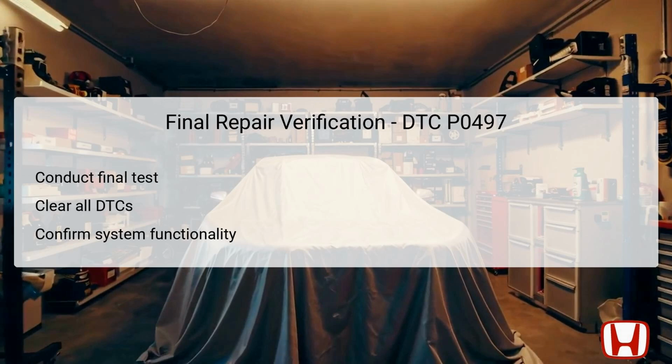Start by clearing all diagnostic trouble codes using the Honda Diagnostic System, HDS, to reset the system. After clearing the codes, it is vital to run the EVAP function test once more to confirm that the repairs have resolved the issue. If the system shows no further DTCs, this indicates the situation has been rectified and the EVAP system is operational.